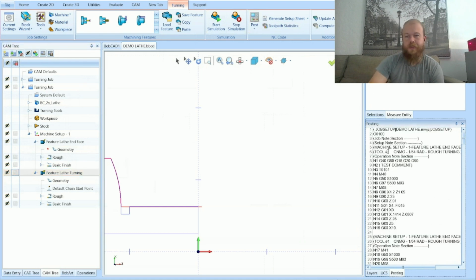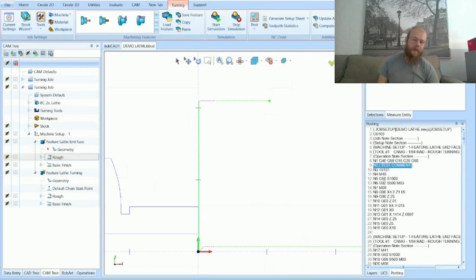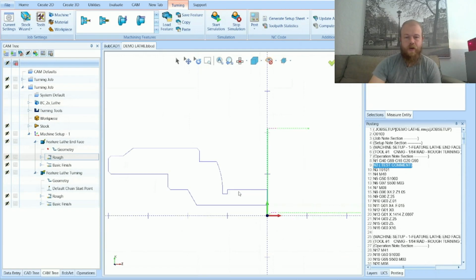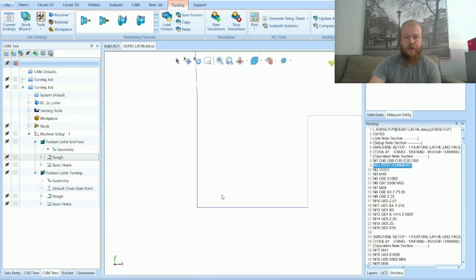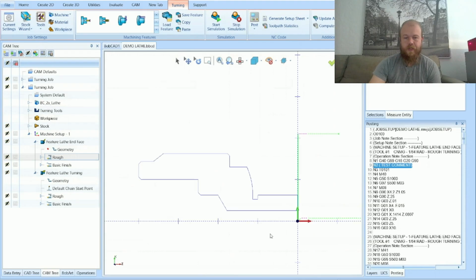And when I hit post, you'll see the G-code for the facing operation, the roughing here that I had with MDI for the test comment. That's added right here before the operation. All right, so covered a lot of ground so far. We'll do the groove operation right here next, and then we'll do the drilling operation in the center here.